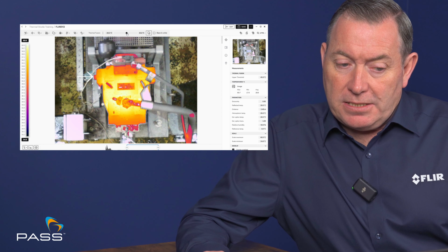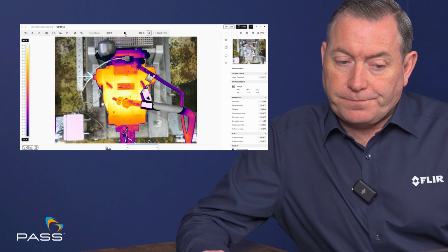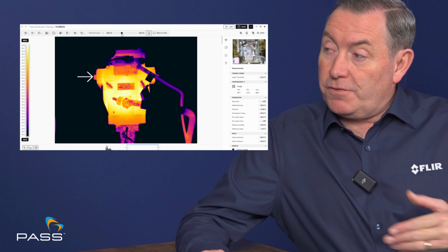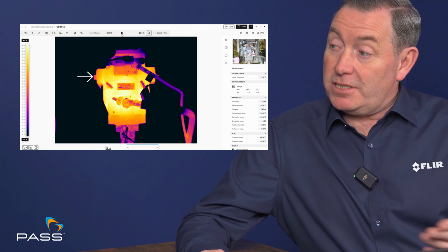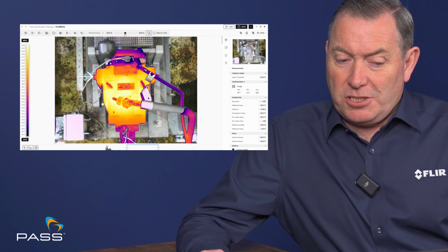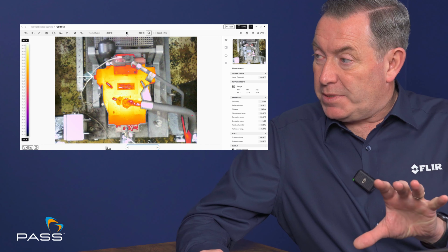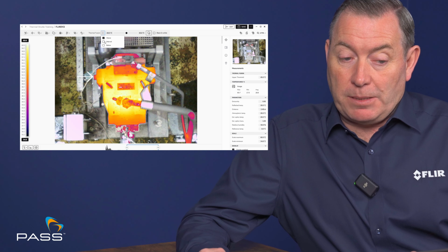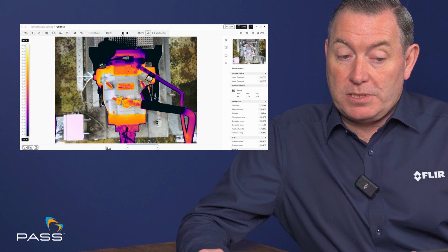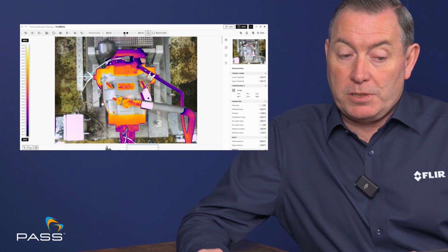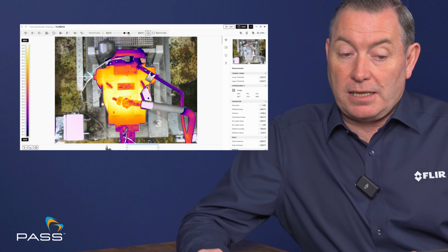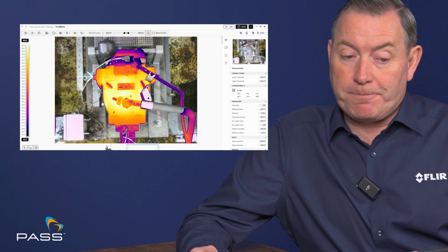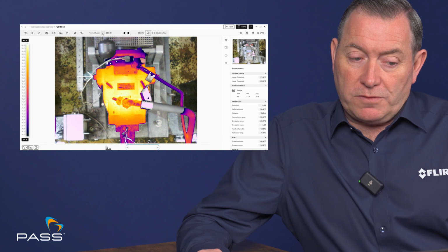Again, it's very easy to choose a different temperature. So why are some areas appearing black? That is if you go too low; you move away from what the data is in the visual image. This is generally used just to highlight an area of a particular temperature which is of interest. And again, it could be an interval temperature, which is between two temperatures. So we can see here we're going between 35 degrees and say 64 degrees, and it's only highlighting as a thermal image, a thermogram. So that's what we use thermal fusion for.